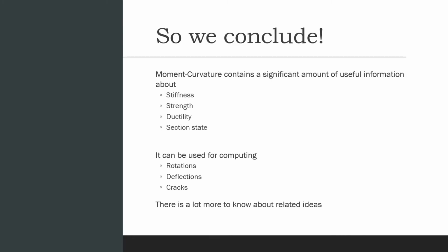We also saw how moment curvature can give us a very good understanding of what's happening to the concrete cross section when it deforms. We saw the stress, we saw when the cover outside the confined zone starts to fail, and when the reinforcement fails and when concrete crushes.